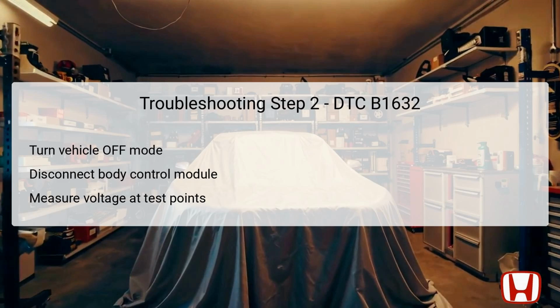If there is battery voltage present, this indicates a short to power in the MTR CONT line, necessitating repairs. If no voltage is detected, you will need to proceed to the next step of diagnostics.